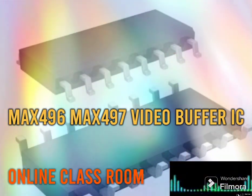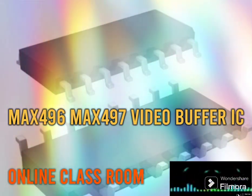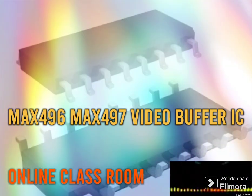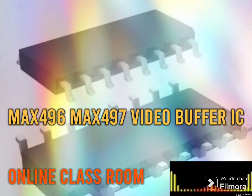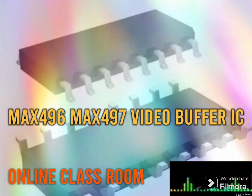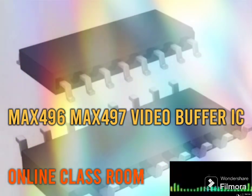The feedback elements that set the closed loop gain are included internally in the device, which helps minimize issues related to board and package parasitics affecting the amplifier's frequency response. The maximum output current of the max496 and max497 is determined by the maximum power dissipation allowed by the package. The maximum temperature at the junction should not go above plus 150 degrees centigrade.